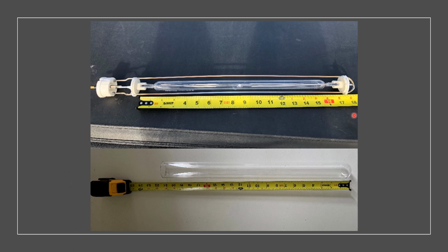Next, we have a picture of an actual UV lamp on the top and its associated quartz thimble on the bottom. The quartz thimble looks like a big test tube. The outside of the quartz thimble is in contact with the water, while the UV lamp sits inside and stays dry. The lamp is never in contact with the water. These lamps run at about 900 degrees Celsius. The operating voltage is around 1400 volts, and the output power is 3500 watts each. A single lamp has 5 times more power than all of the industrial lamps I used in the small pilot study combined.